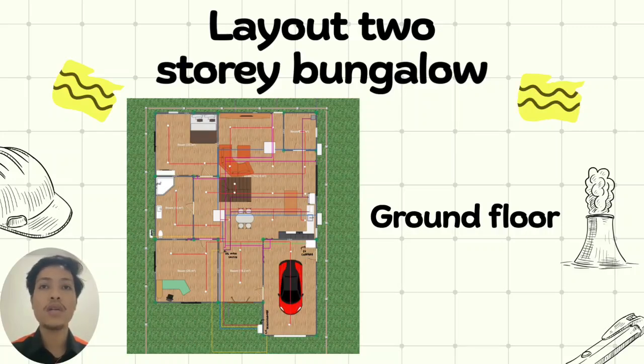Starting with the ground floor, the power distribution mainly supports common and functional areas where electrical demand is relatively higher. Separate circuits are provided for lighting and power sockets to prevent overloading and to improve safety. This design also allows easier troubleshooting and maintenance if any fault occurs.